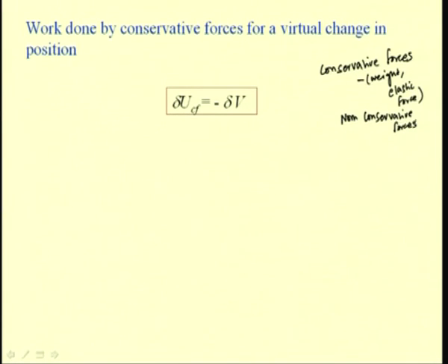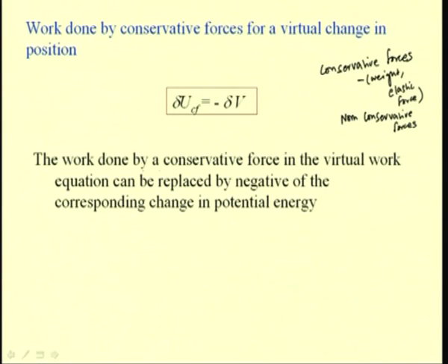So, in the active force diagram, we can remove these conservative forces, that is the weight and the elastic force, and only consider the non-conservative forces to compute the virtual work. And the work done by these conservative forces can be replaced by the negative of the change in potential energy of the system for that particular virtual displacement. So, we say that the work done by the conservative force in the virtual work equation can be replaced by the negative of the corresponding change in the potential energy.